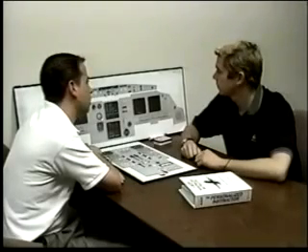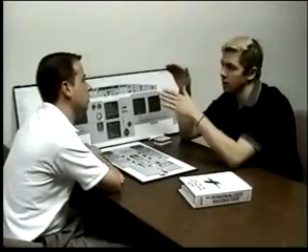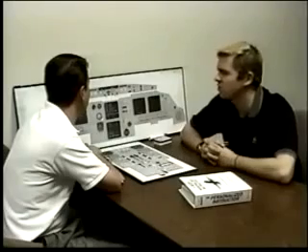How about if the autopilot kicks off? The autopilot kicking off is really a player for after we've taken off and I've engaged the autopilot. We don't want to inhibit it up to 1,500 feet like the rest of them are, so we just don't inhibit it. If I take off and start a turn and the autopilot kicks off, we still want to know about it. So that one is one of the strange ones that hangs out there. Takeoff inhibit is active from takeoff power application up to 1,500 feet.